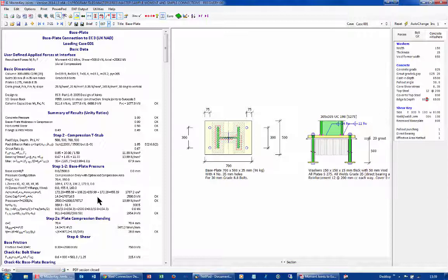So if I increase that to 1500, we're hitting this 1.85 still, but if I increase this to 1500, I'm now up to a pad diffusion ratio of 3. So that's an enormous improvement in my base plate bearing capacity, because I can now take 22.7 newtons per millimeter squared onto this base. So I'm going to go back to a more average 500 and 500 deep pads or 450 deep pads and come on down through the design. So that's very simple.